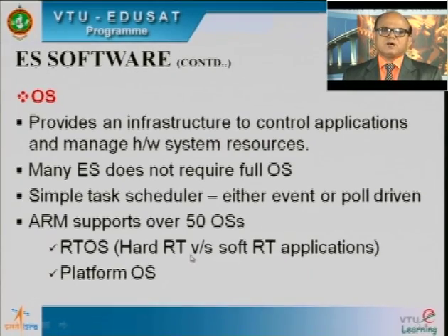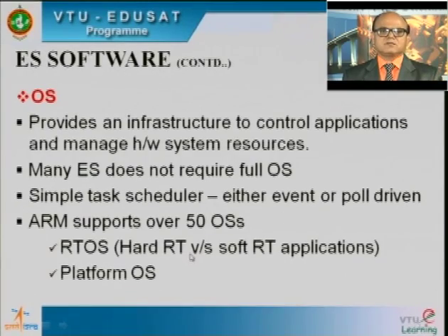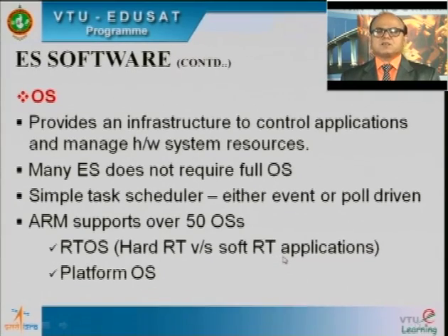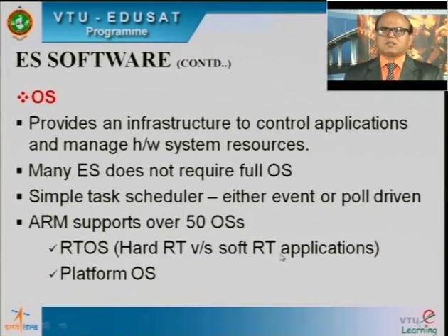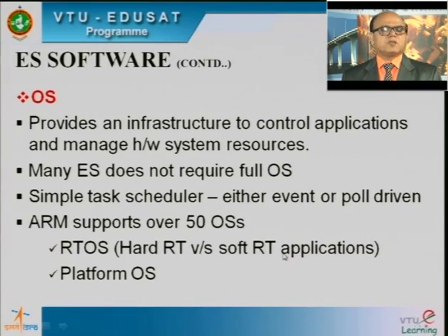Hard real time always expects a certain event or signal to be completed in a stipulated time exactly. Such a requirement has to be honored by hard real time operating systems. In soft real time applications we have a similar requirement, but a slight overshoot or undershoot may degrade the performance without being a threat to the system.